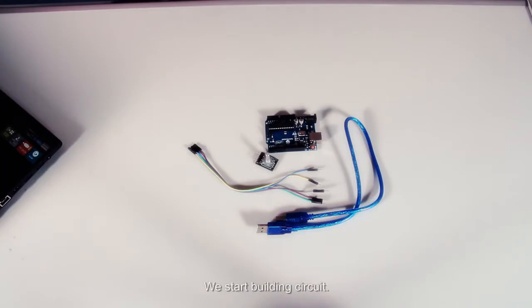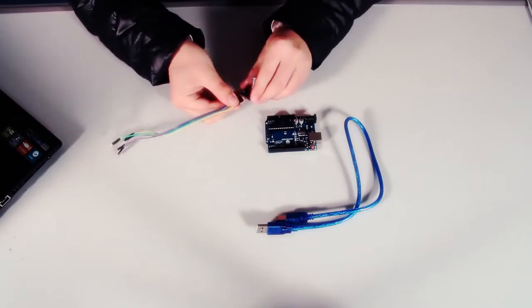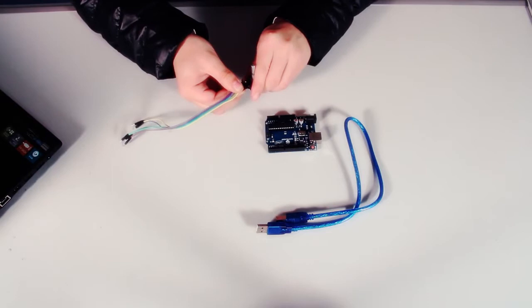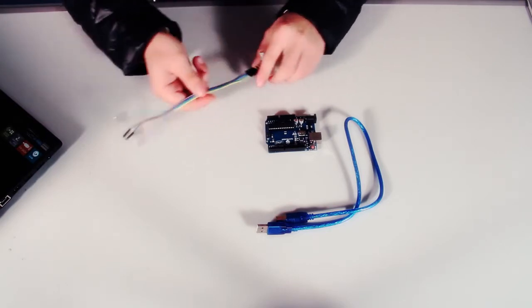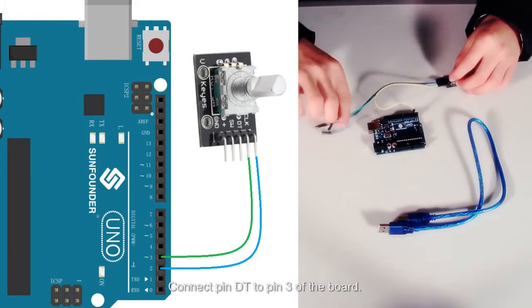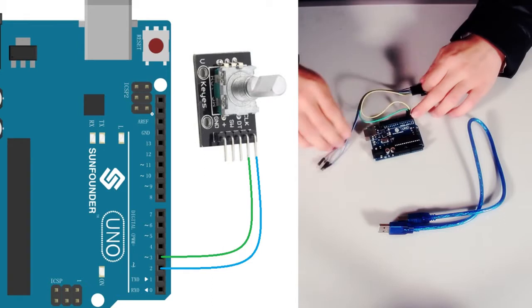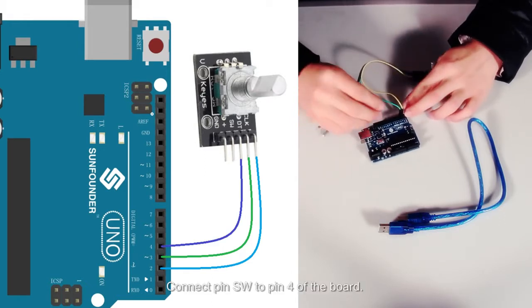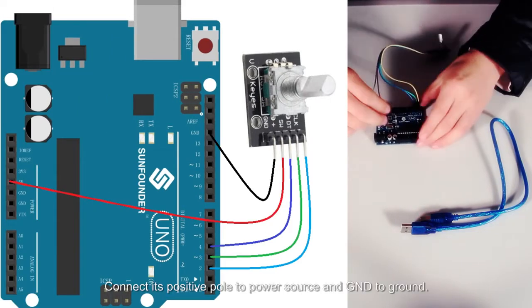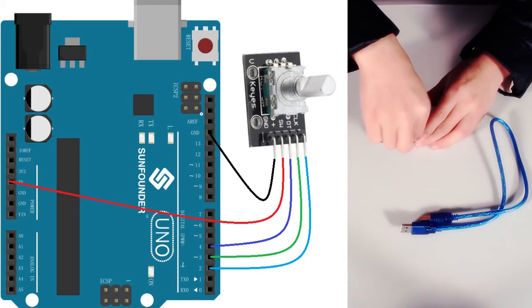We start building the circuit. Connect pin CLK to pin 2 of the board. Connect pin DT to pin 3 of the board. Connect pin SW to pin 4 of the board. Connect its positive pole to the power source and GND to ground.